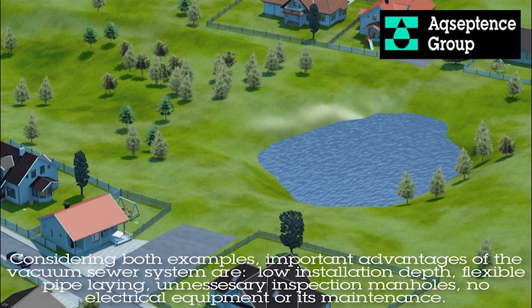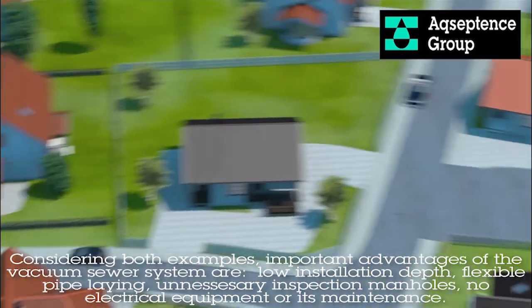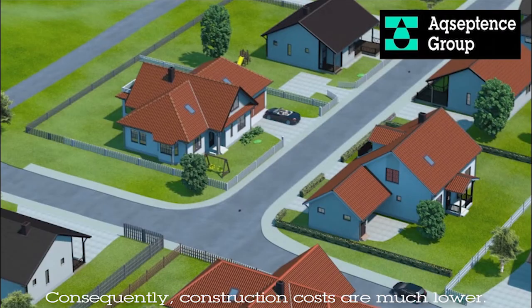Considering both examples, important advantages of the vacuum sewer system are low installation depth, flexible pipe laying, unnecessary inspection manholes, no electrical equipment or its maintenance. Consequently, construction costs are much lower.